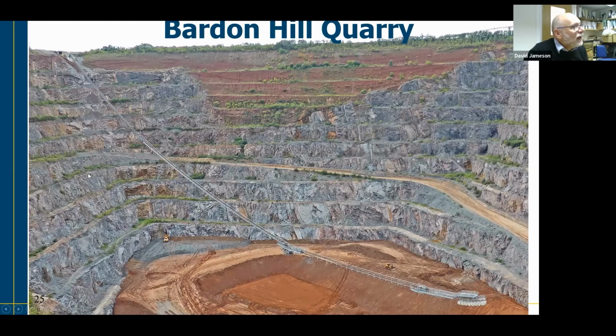And the task there was to consider the size of an adequate rock trap, which would need to be designed in order to contain any of that rockfall, not only as it was being excavated, but also in the future to allow for access to the floor of the quarry, because you need to service your vehicles and bring fuel and all the rest of it down to the bottom.